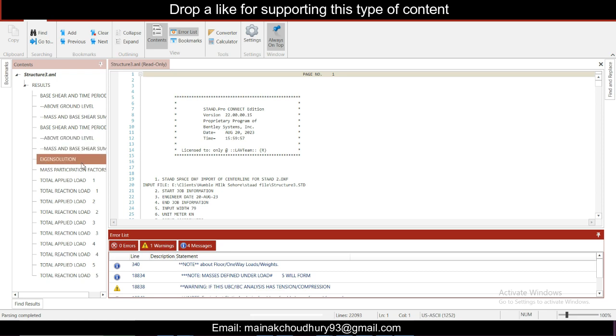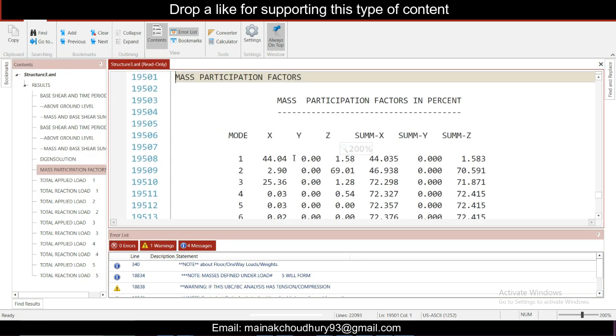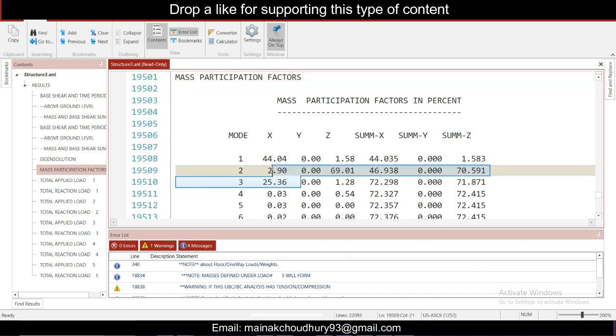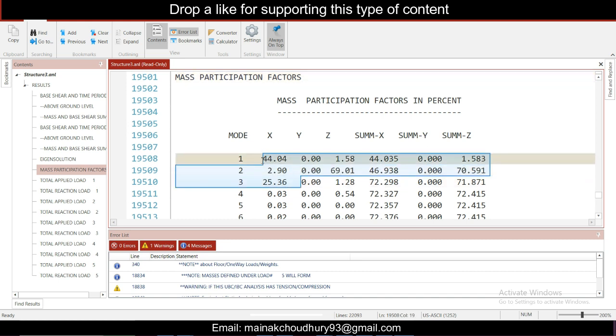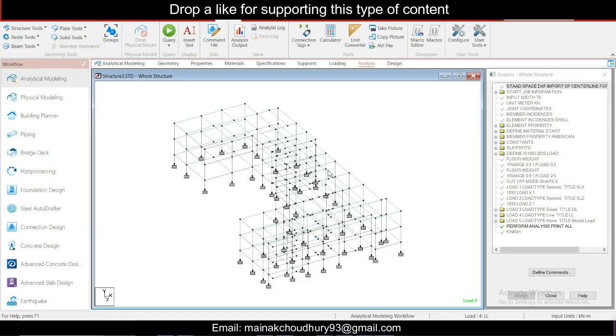Let's see the mass participation factors. Double click on this, so we'll see whether it is 65% or not. According to the IS code, the summation of these three should be more than 65. 44 plus 22, so it's okay. It's more than 65%, so it's okay. So just close this.